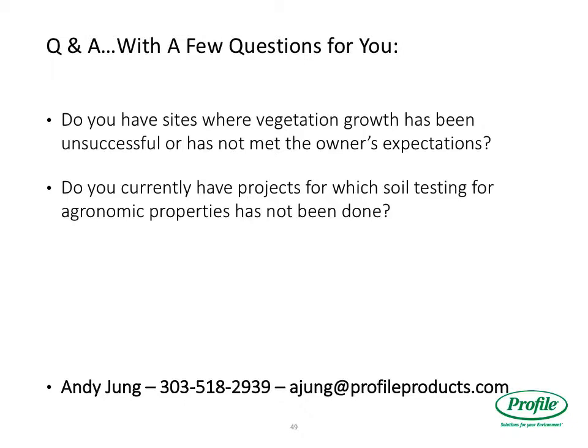Have you documented water quality improvements just from vegetating a waste rock pile, or is it just for erosion control? The question was, have we demonstrated water quality improvements through sustainable vegetation? I think the biggest one would probably be for an ET cover where you're limiting the infiltration. That's going to be more of a groundwater issue than a surface water issue. But if you have that storage layer and you're keeping water from migrating into the tailings or the waste rock and leaching material out, you can prevent that migration without using a liner. I'm not sure of any instances where we can demonstrate that we improve surface water, but certainly groundwater.